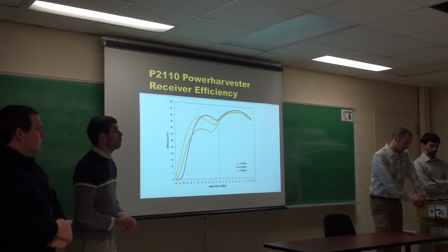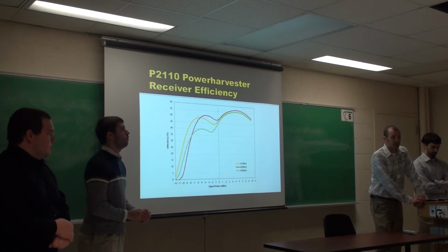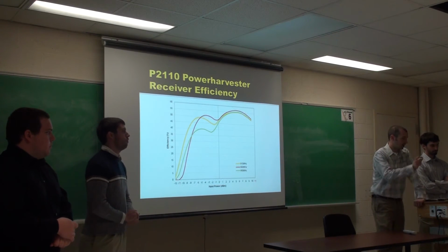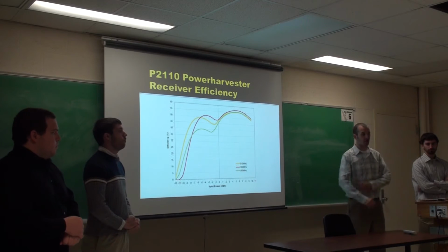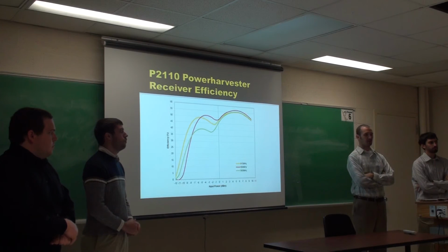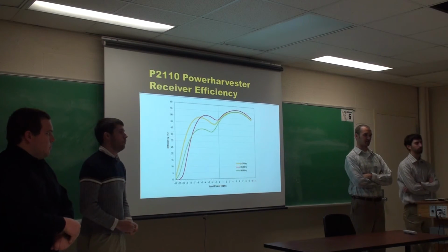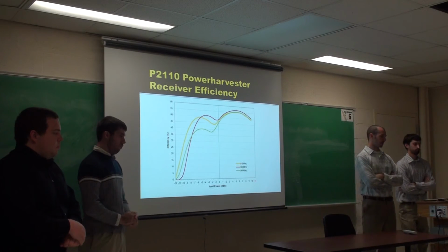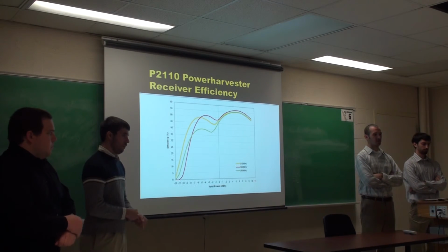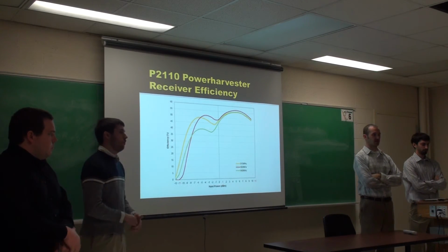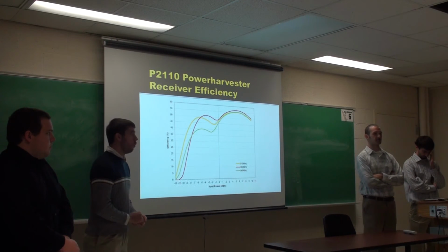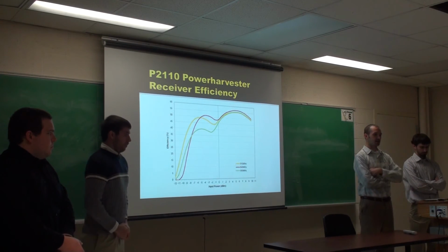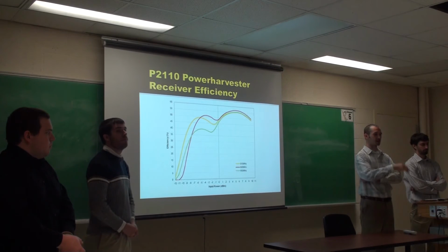Well, I think I know what you're saying. Going about obstacles with any RF signal, no matter what, is going to provide a little bit of loss. So having a clear path is obviously going to improve the efficiency, but with that 915 megahertz frequency, it usually is very good at cutting through, and also the band that it gives and the antenna provide a bigger range of what it can capture.